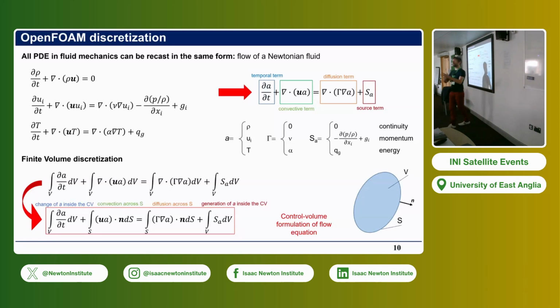It may work better or worse depending on the specific properties you're solving, but you can develop a discretization method and call it in OpenFOAM with its own name that you define. So if you want to solve 3 equations with a new discretization method you create, you don't need to discretize it in each equation. You make a library for it, and then you call it up.